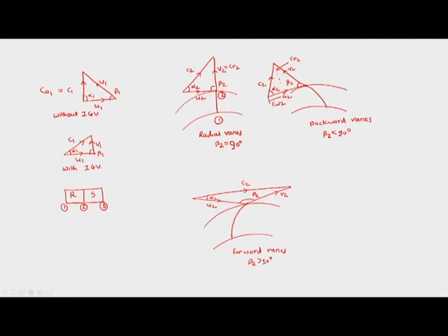So we had seen that there are three options for the outlet velocity triangle and two options for the inlet velocity triangle. Having said this, we should now find out what the outcomes of these velocity triangles are. First, we should know what W is for a stage, that is the work input for a stage. That work input for a stage we know is m dot into (U2 CW2 minus U1 CW1), but we will consider it to be specific work input.